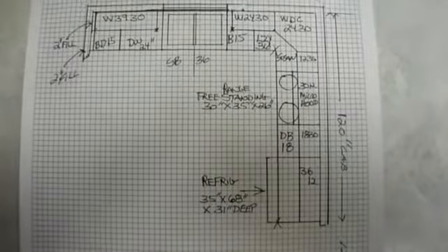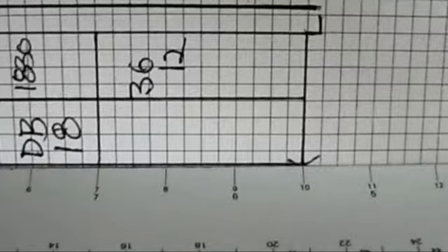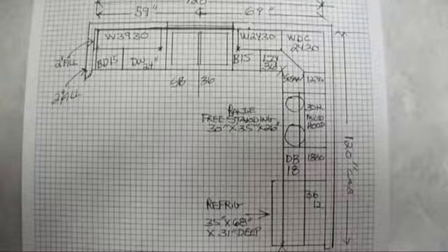The reason we have a spacer is it was 128 inches, but we have 126 inches of actual cabinets. There's 2 inches left over. And since we work from the center of our window, and we work from the right to left at an even 69 inches, the balance is pretty obvious that it's on the left-hand side. And that was that 2 inches.